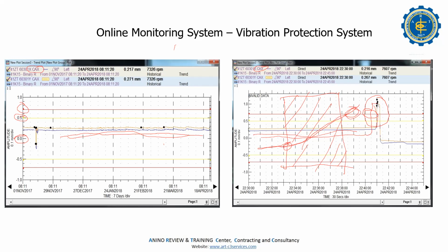So it has too much vertical vibration, the velocity is too much going up. So then they stopped the fan, then they cleaned it, because we don't want the fan to have residue on the vanes so that the vibration becomes worse. Suddenly what happened, every day I was monitoring, suddenly I saw the g's values had gone to 73 g's.